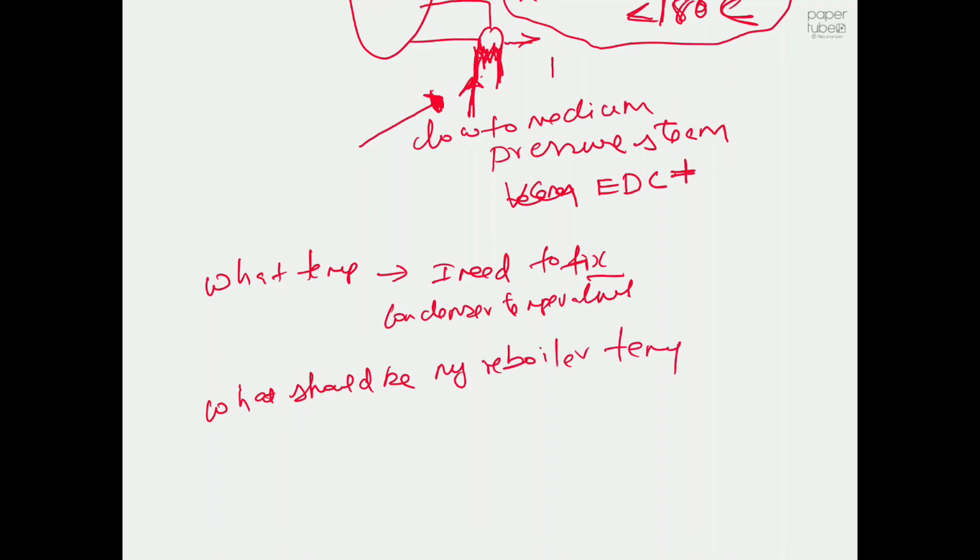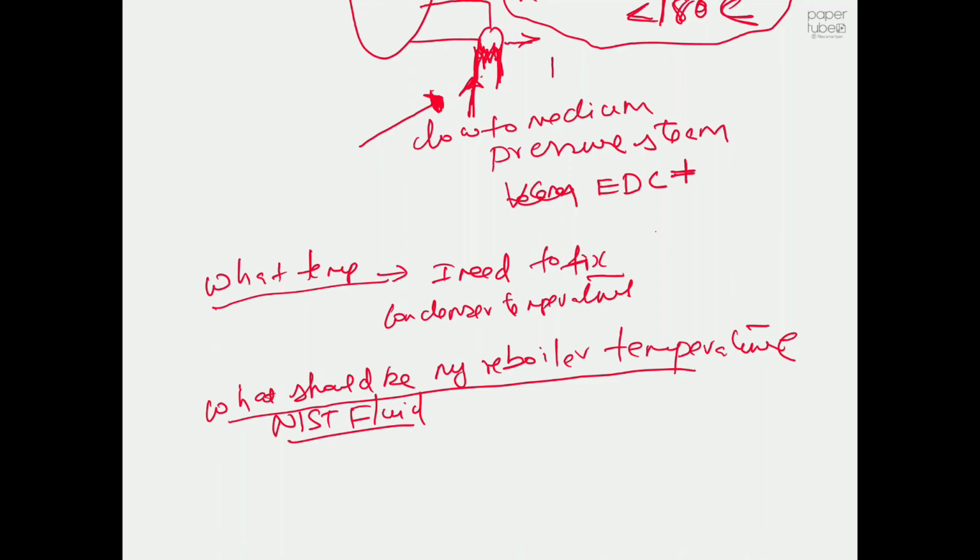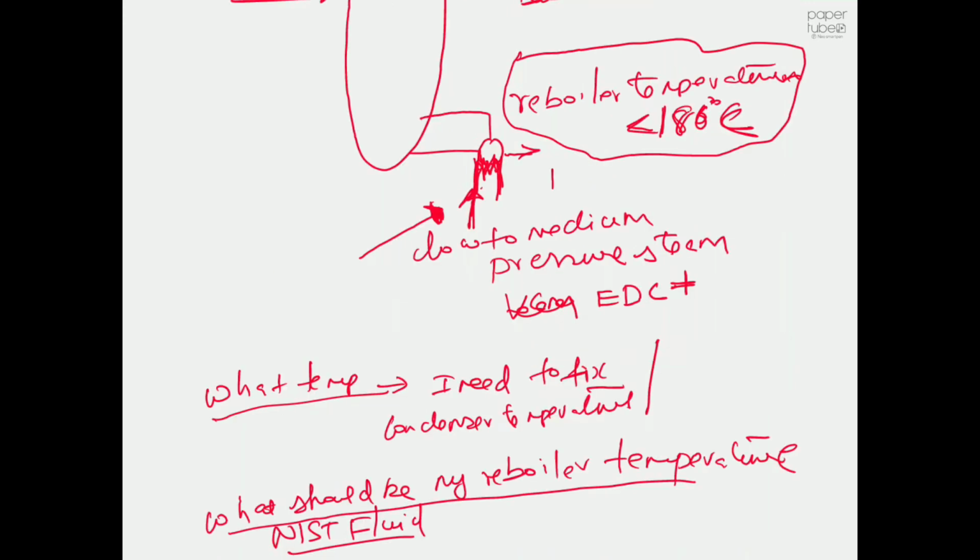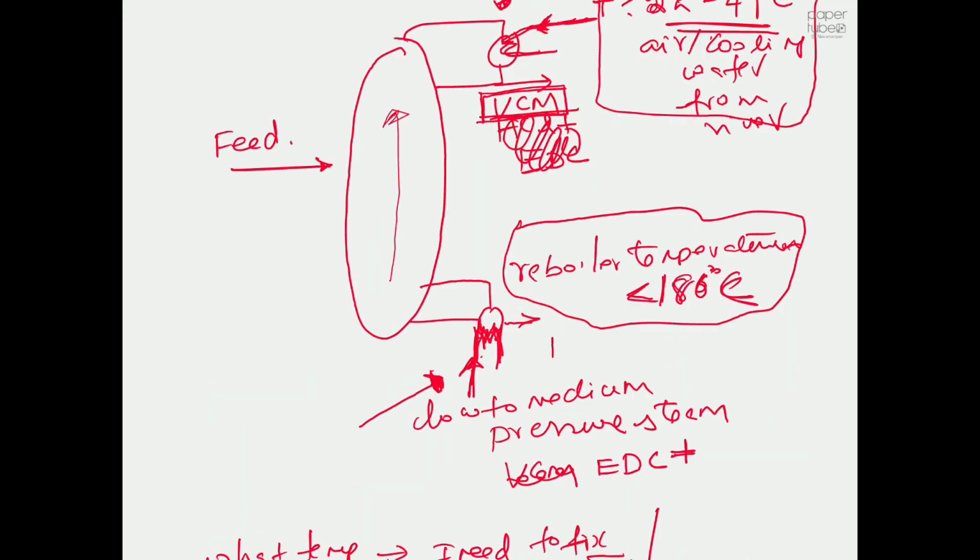Obviously we can get some idea from standard textbooks, or we can go to NIST, but we will use Aspen HYSYS to get these values. We will see what temperature we need to maintain in the condenser, and what temperature we need to maintain in the reboiler, that ensures you will get vinyl chloride monomer in the top of your column.